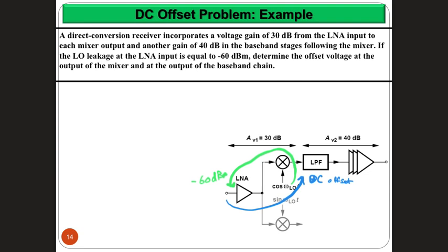If it were 20, 10 to the power of, over 20. Is it because before rectification it will not be DC yet, it will be a rectified cosine, like squared cosine? It's cosine, it's not DC. The rectification will happen when you multiply here. When you multiply the cosine by the cosine, you get squared cosine, which is a cosine at double frequency and DC. Both of them, but he wants the DC only.